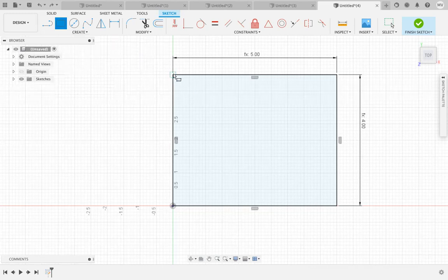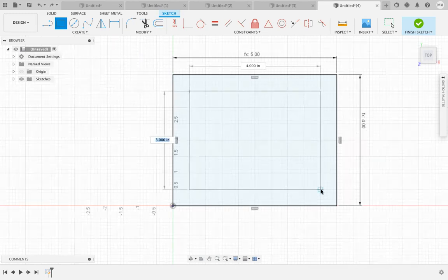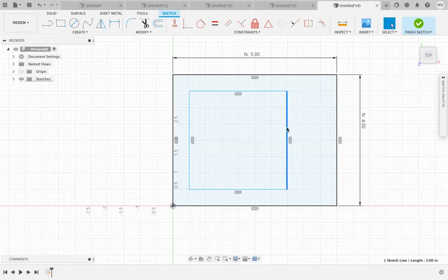Some people just started counting squares and placing this, and then count squares over here, and let's place that. Okay, that's exactly in the middle. This is great, but it's all blue. Why is it all blue? Well, if I click on any one of these sides, I see that they don't have to be there. I could move them. So we haven't fully constrained this sketch yet.